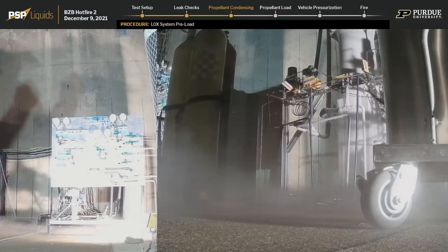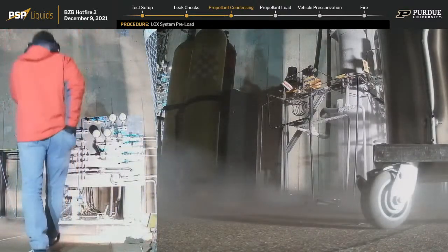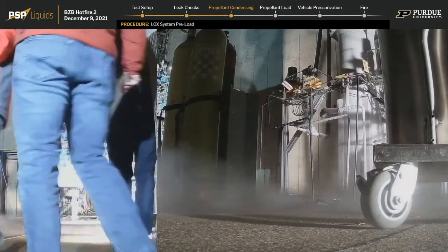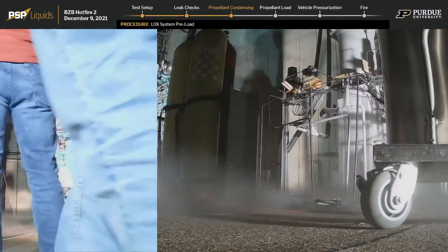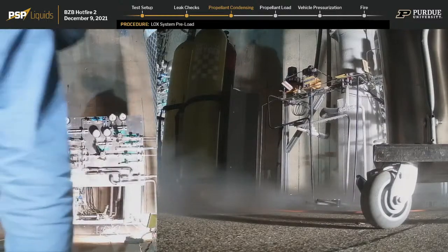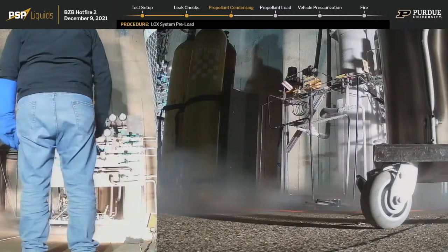Right. The dewar's at 100 psi. Over. Copy all. Let's go ahead and move on. Go ahead and open MV Aux 01, the liquid valve. And I believe in this specific case, it is for making sure a cryogenic fluid is actually a gas before it hits that specific valve.